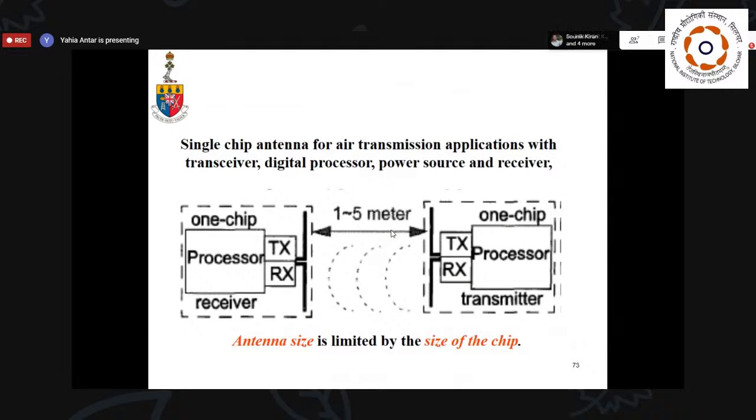For on-chip antennas and so on, there are quite a few requirements on their size because you can't have a big real estate on the chip. So the dielectric resonator gives you an advantage in that, because if you compare the size of the resonator with the microstrip antennas, obviously there is the advantage of the smaller real estate the resonator buys.